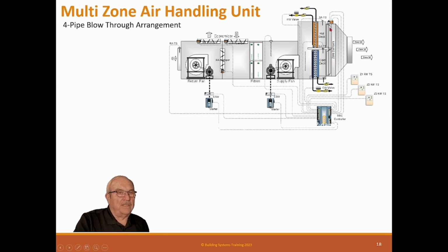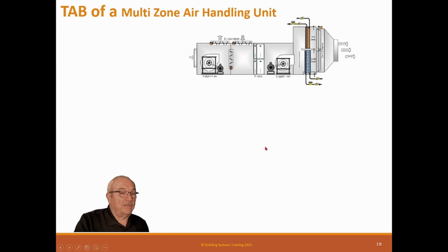The way they size these is this actuator may be controlling 3 dampers. So you put on the face of this unit a whole bunch of dampers, maybe 20 dampers wide. And then for each zone, depending on how much CFM, you link them together. So on one, you may only have 1 damper, the next one you may have 4 dampers, the next one you may have 11 dampers. And they did that just to verify the size of the zones. So cost is a limiting factor in a multi-zone.